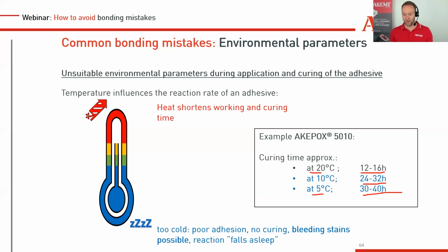So this can happen. The second thing is, when it becomes too slow, there is also not a good curing, and because the glue stays liquid for a long time, you can cause some bleeding, which we said earlier, left and right on the bonding seam. You can get some dark discoloration because the glue never really properly gets hard. So all the liquids start moving into the stone.